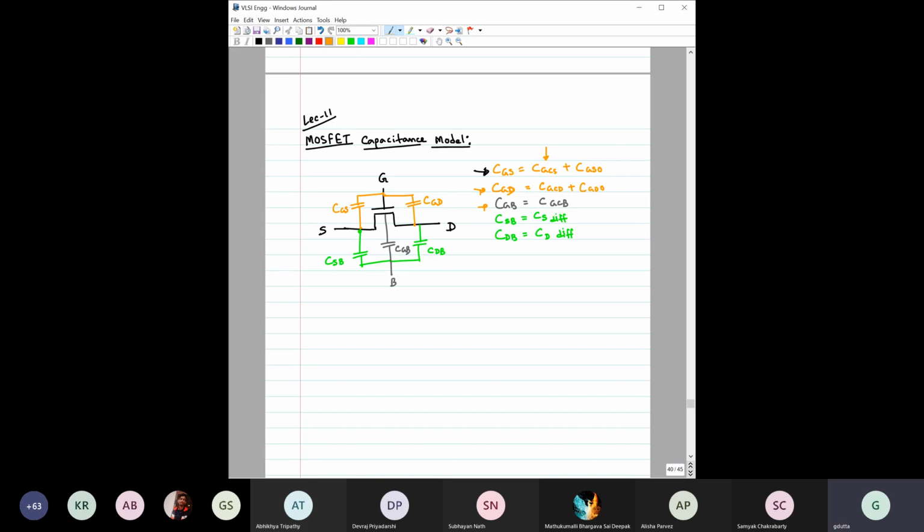Now, one of you has asked, and I just wanted to clear up that when the transistor is in cutoff, say at Vg equal to 0, how can it have a capacitance? It does not matter what the DC biasing condition is. Even if the bias applied between these two terminals is 0, there is still capacitance. Capacitance does exist; it does not depend on what the DC voltage across that capacitor is. Maybe we will have more discussion tomorrow regarding when and how these capacitances are measured, that is, if you have to measure any capacitor, how do you do that?